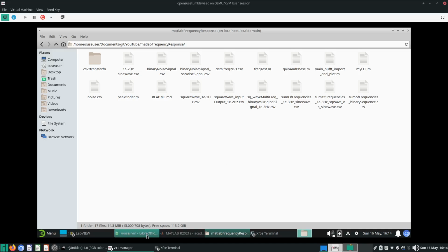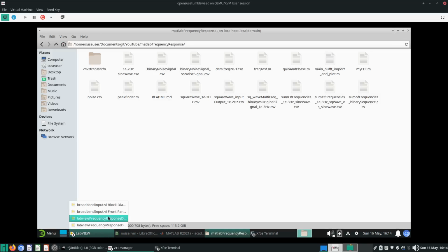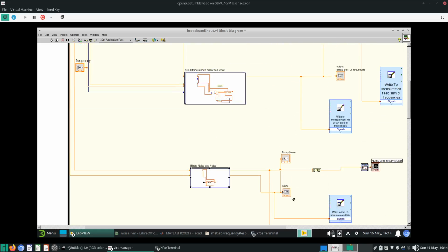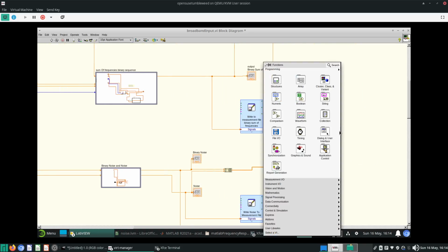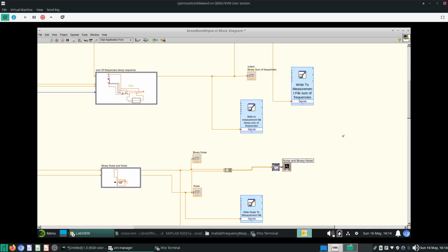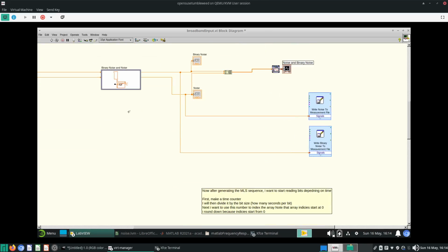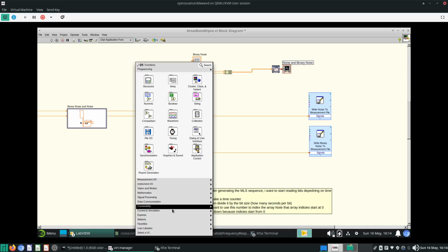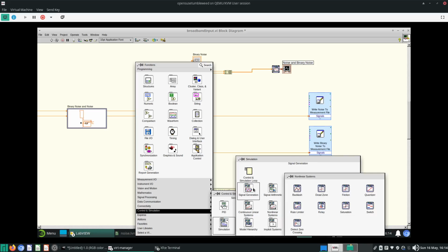The demonstration just now shows you what the noise looks like in the Fourier transform, the fast Fourier transform. If you don't want all the noise, you might want to use a filter. So I can cut off all the higher frequency signals and just go for the lower frequency signals. How do we do that? One of the ways is to just use this transfer function.